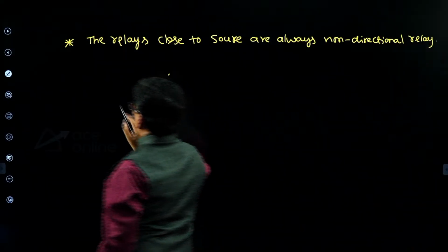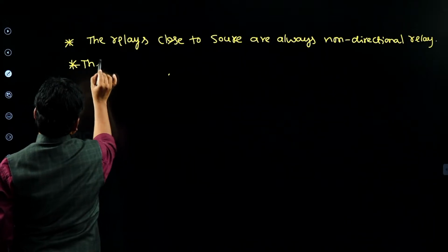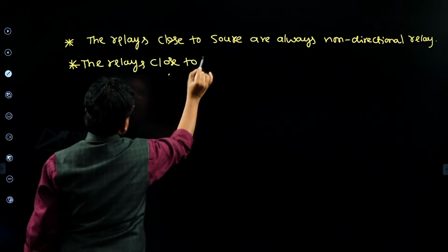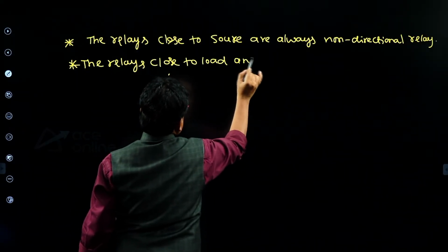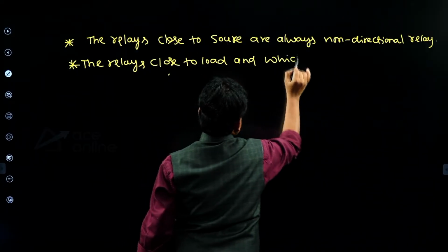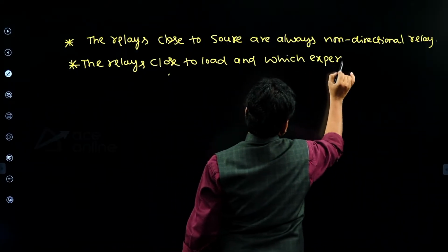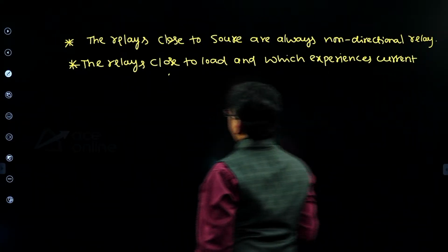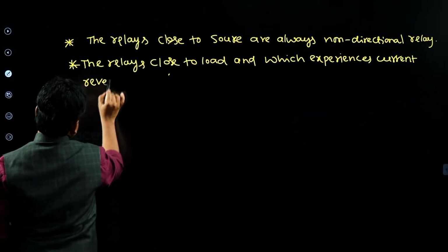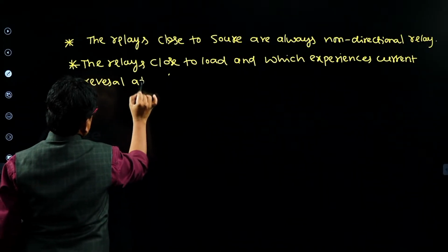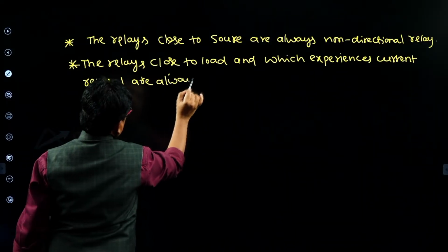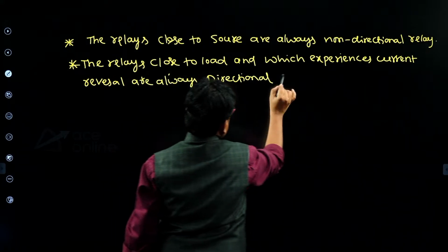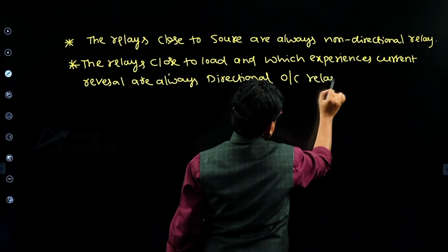And the relays close to the load, which experience current reversal, are always directional overcurrent relays.